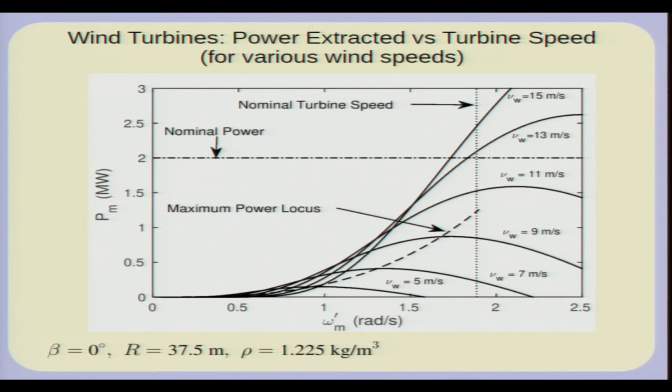Now, the important thing is how the rotational speed of the turbine is determined. What is the turbine connected to? The turbine is connected to a generator, and the generator is usually directly connected to, say, a grid. Let us say it is connected to a grid of 50 hertz. Now, you have a generator which is connected to an AC grid of 50 hertz.